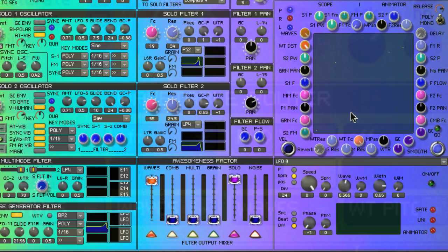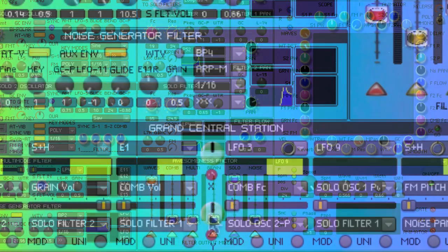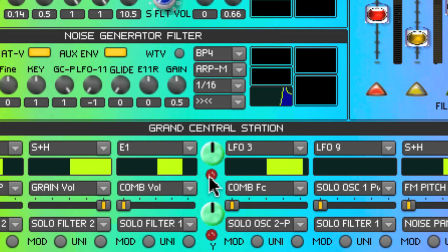The last thing to talk about is controlling the pad from a modulator. That's a little different because what we're going to do is we're going to have a modulator source in Grand Central Station transmit messages to the pad. We can leave everything else set up here, but what we have to do is activate these transmit buttons, and now we have transmit ranges for a positive or an inverted transmission value. So we'll just set these both up to positive full.